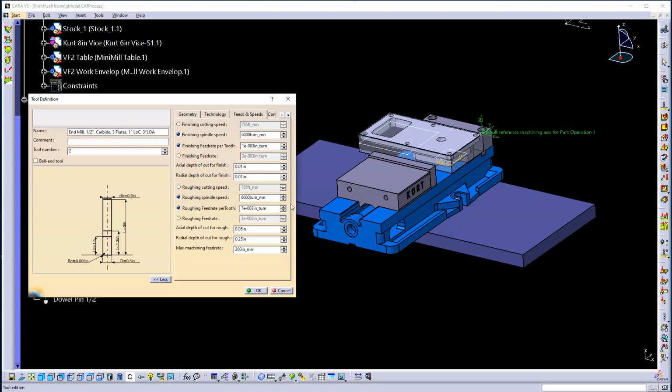And so you can cause a lot of harm, or you can make a lot of things better just by adjusting it right down here. Now, sometimes within a machining operation, we will choose a specific set of feeds and speeds for that operation only, and we will unlink that usage of the tool from this tool definition, but that won't happen all that much. We would rather change it here and have it propagate all the way through.